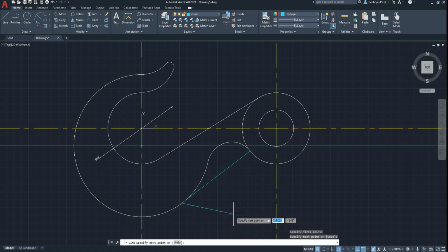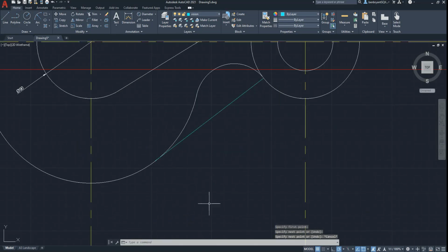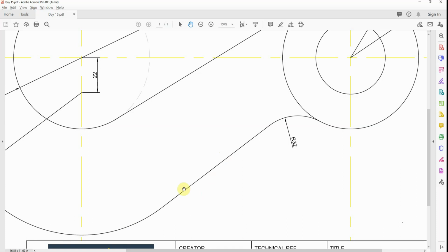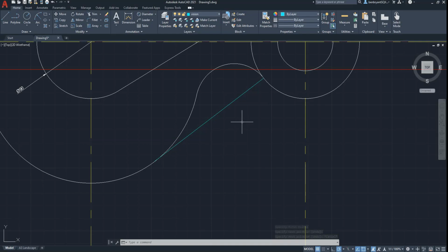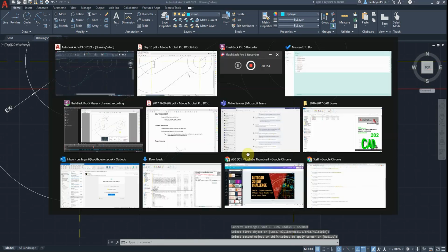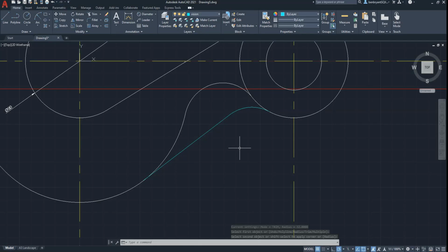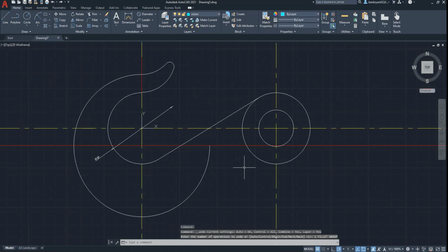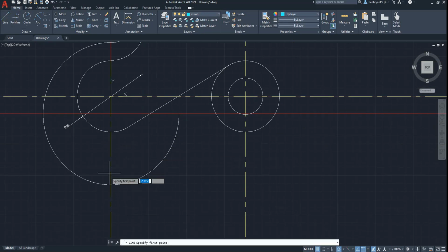What I can then do is pull the tangent point on that section. So when I come back again, I've got that tangent. The line technically starts there, which is exactly where that is. Now when I come back into fillet again, choose one, choose two, it puts that fillet back in place. So now technically you could argue that you don't really need that first section, because all I'm really doing is just drawing a line from one point to the other, but because you have that fillet in, I'll have to do it again now because I've just undone it, but fillet